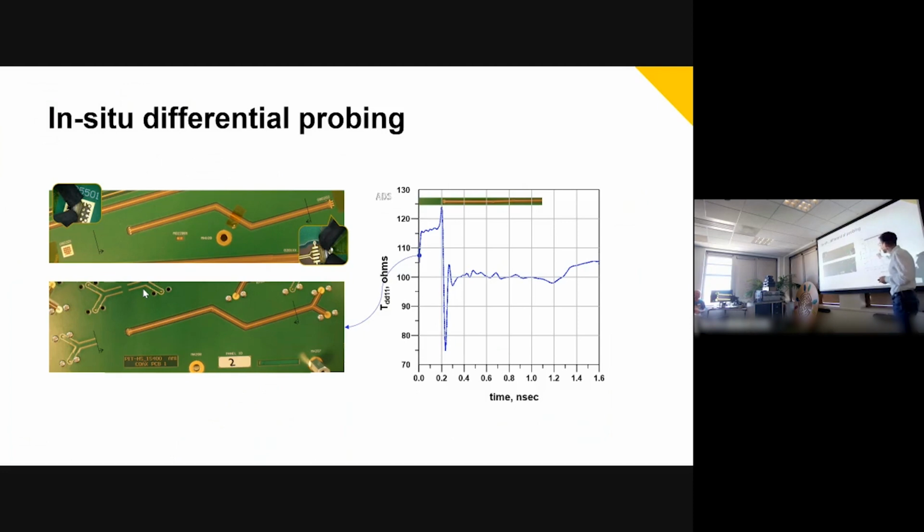Our reference truth in blue. So what you can see is that the strip line part is more like 116 ohms or something, which is not what we ordered. So there's a problem. And then there's the via, and after that about 100 ohms. If you look carefully, you can even recognize the 45-degree bends as small bumps here. And now we're going to look at the in situ probing. Now, here you see some deviation, but the 116 ohm problem is clearly identified. So the point I wanted to make here is, yes, it's not ideal in a sense, but it is ideal in the sense that you do not need to think about this beforehand. That is possible.